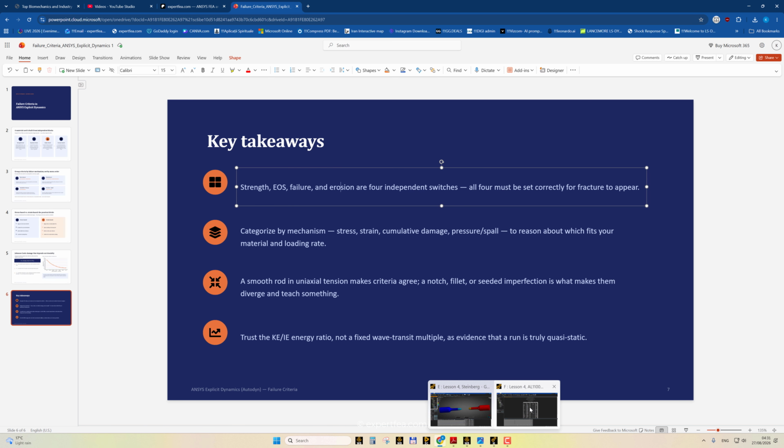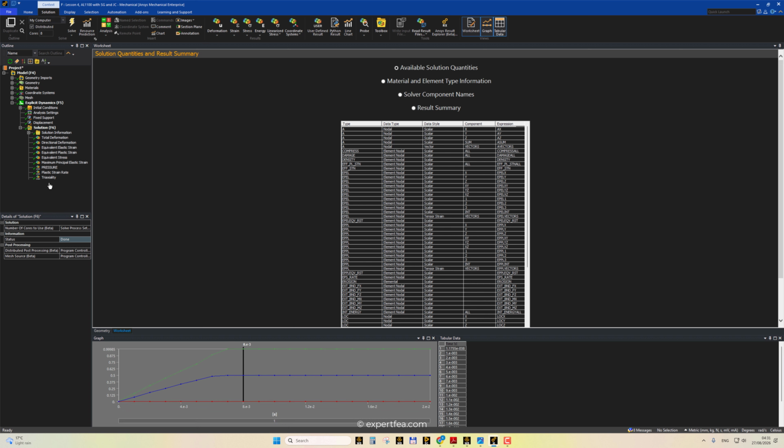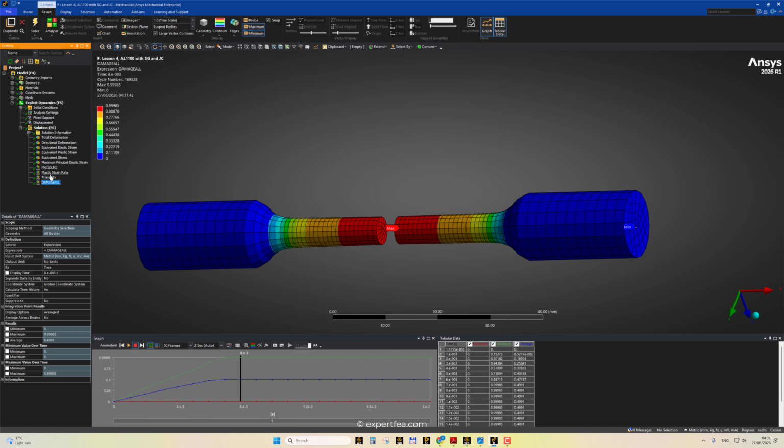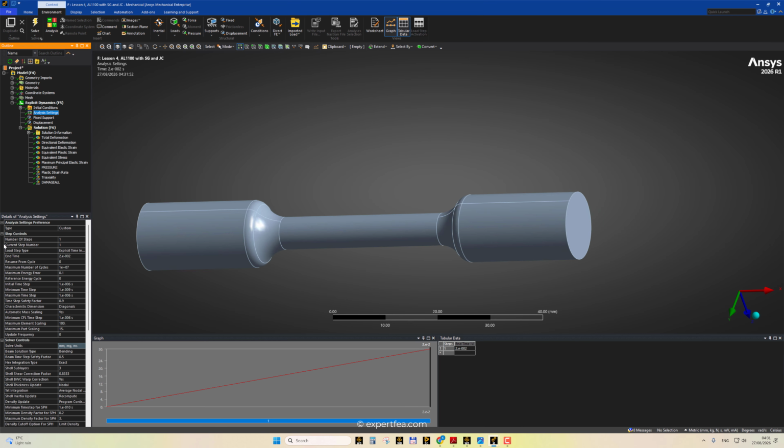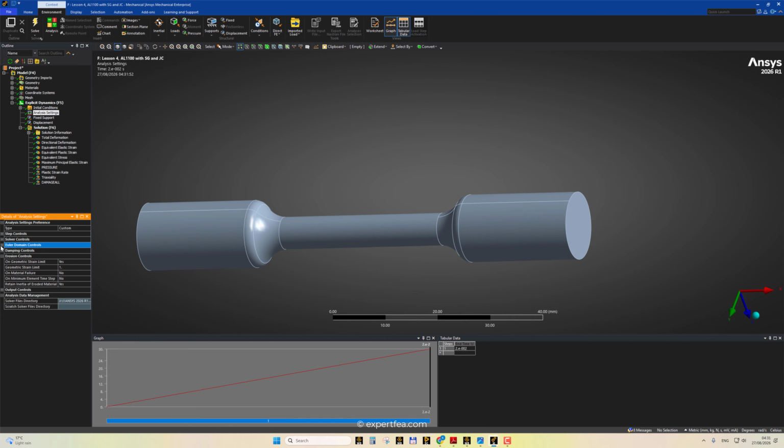A small remark regarding this last simulation, from the cell F. I have decreased the geometric strain limit. 1.5, the default, is not always useful, and I know from experience that it should be decreased, because 1.5 was too much for this scenario.